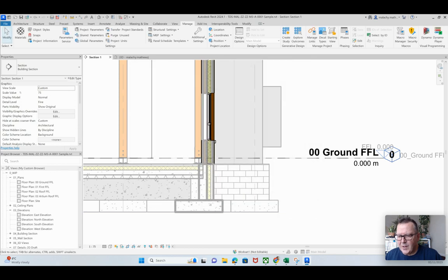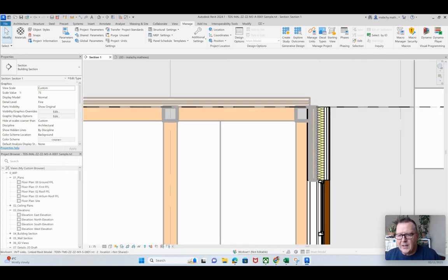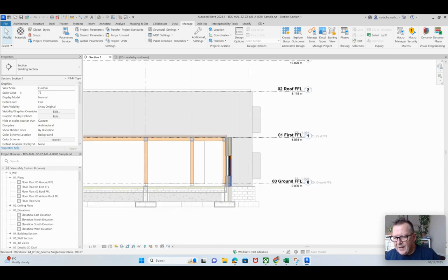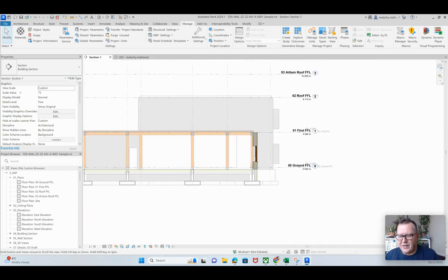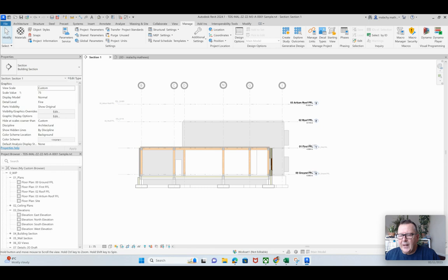Look, so that's what I mean. You might need to do a little bit of playing around with some of the line thicknesses here. And the object styles are global, so wherever you change them there, they will update. Yeah, and the beams are cut quite big as well. But they are when you zoom into it, but when you zoom out of it, actually, it's not too bad. Yeah, it might just cut down the cut section on those a little bit more, rather than 6, might go down to 5 or something like that. All right. There's that perennial problem of this here as well, and I will show you how we're going to solve that in probably the next video or so.